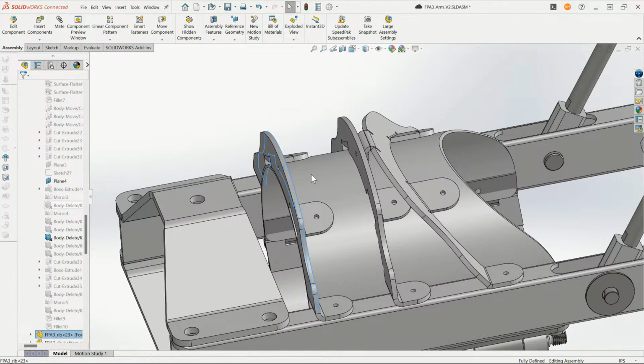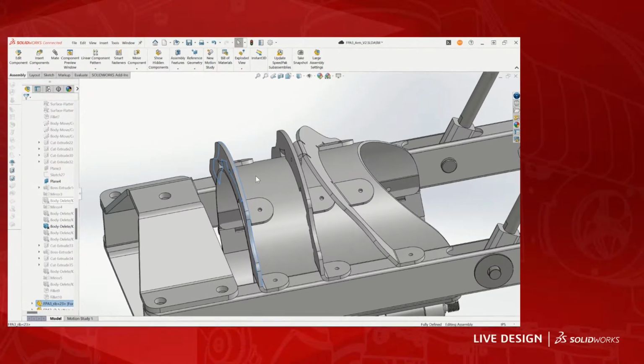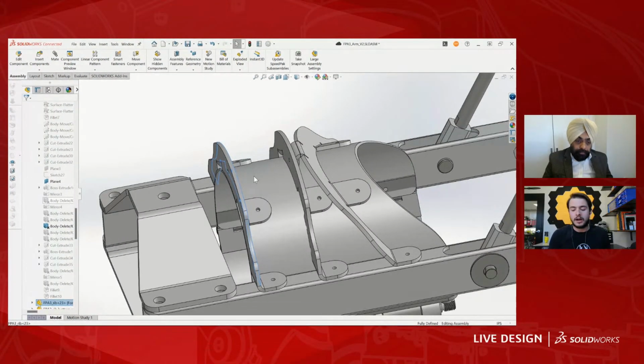I guess before I even get into that, why sheet metal, right? Basically, 3D printing is great, but 3D printing in most cases is limited to plastic. Metal 3D printing, very expensive, pretty slow, hard to iterate on. With sheet metal, not only can we do things like wood or acrylic, but we have a fiber laser cutter, which can do up to, I think, 18 millimeter steel plate. So we can do about 3/4 inch thick steel plate and make some very strong parts very, very quickly.